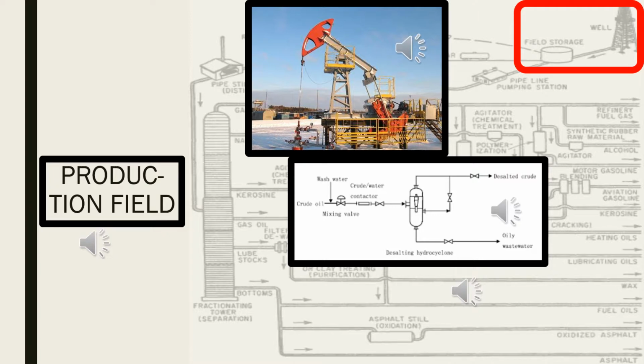If the petroleum from the separators contains water and dirt, water washing can remove much of the water-soluble minerals and entrained solids. If these crude oil contaminants are not removed, they can cause operating problems during refinery processing, such as equipment plugging and corrosion as well as catalyst deactivation.